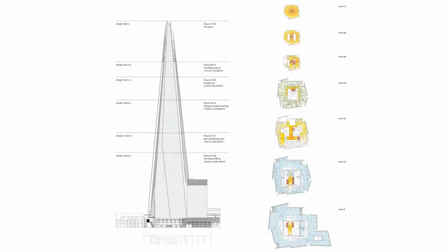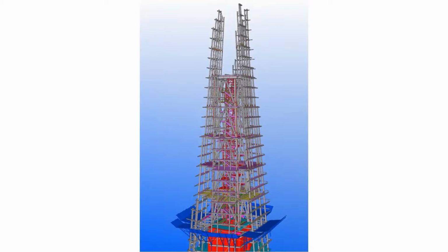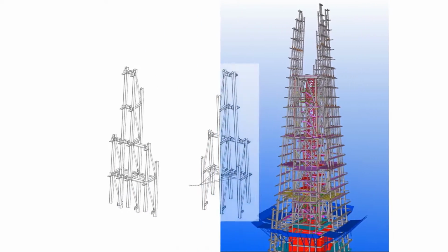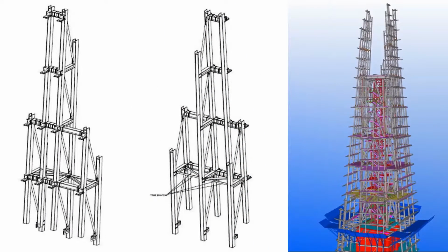And because of small area, high height and fast wind, this huge steel structure could not be made at the site. So engineers adopted the module method. To lift modules, each module must be lighter than 7 tons, which is the capacity of the tower crane.